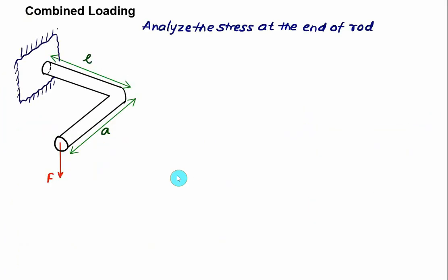When a machine component is subjected to only axial load, or only bending moment, or torque, a uniaxial state of stress is produced, which we have discussed up till now. But in actual practice, the components are mostly subjected to a combination of loads. For example, if the transmission shaft is subjected to bending and torsion at the same time, combined loading leads to a complex state of stress.